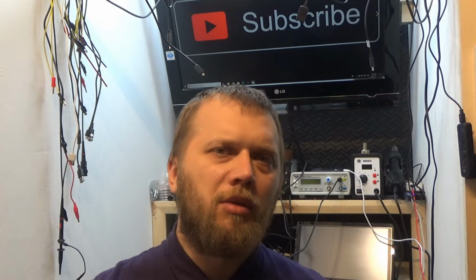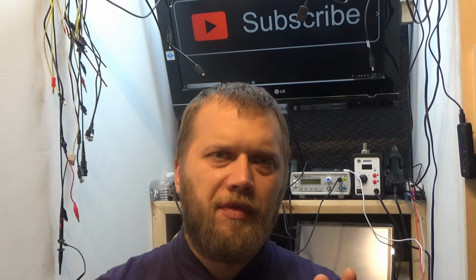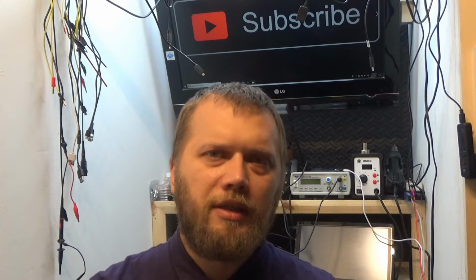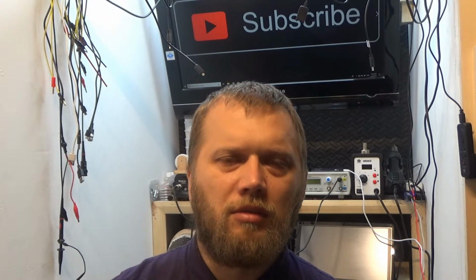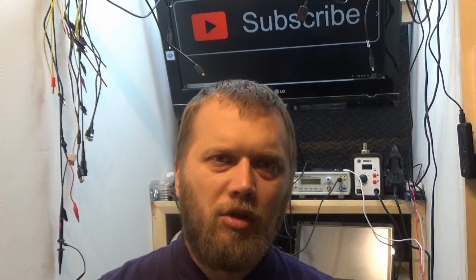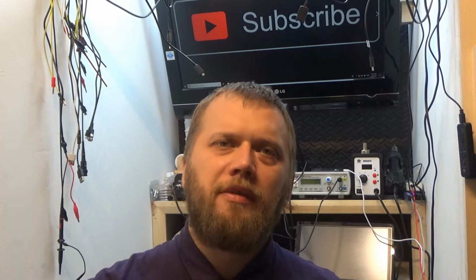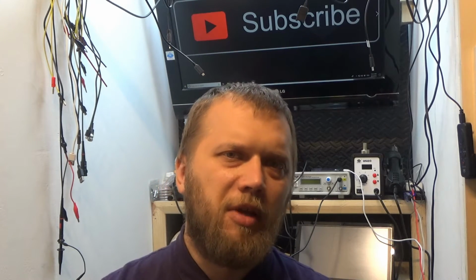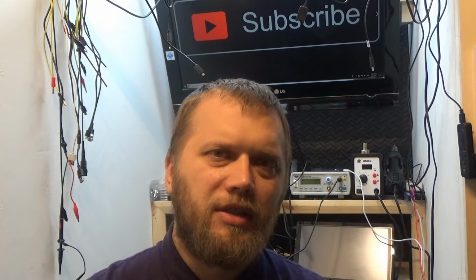Now, if you're dealing with only one type of waveform, for example a sine wave, it is possible to calculate the RMS value of that sine wave, and it will be reasonably accurate. And that's what averaging multimeters do. They have a lookup table of some sort inside the microcontroller. They measure peak value and they look up the value of the RMS signal for that, and that's what they display on the screen. However, a true RMS meter works entirely differently.